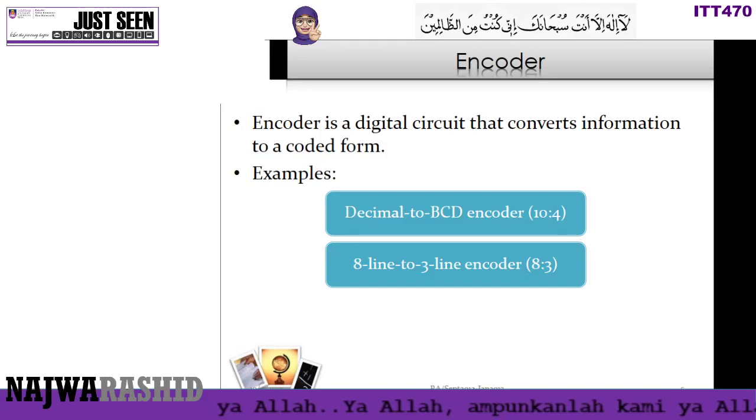Okay, this video will explain and discuss the encoder. An encoder is a digital circuit that converts information to a coded form. Examples of the encoder: we have decimal to BCD. In decimal we have 10 numbers, and in BCD we have 4 bits of binary, so 10:4. And then we have the 8 line to 3 line encoder, where we convert from 8 into 3.